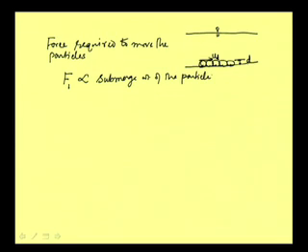Now, starting with that, what will be the submerged weight? We can write F1, and introduce a proportionality constant, say A1. The weight will be proportional to the volume of the particle, and the volume will be proportional to the diameter cube, d cubed.